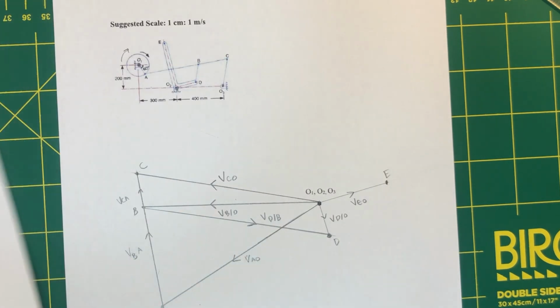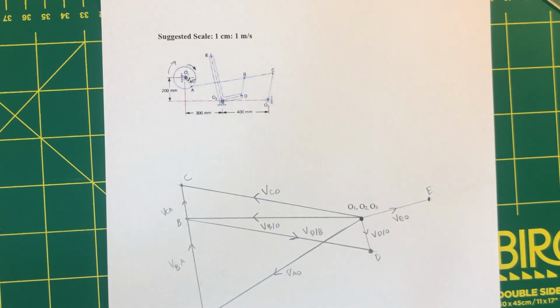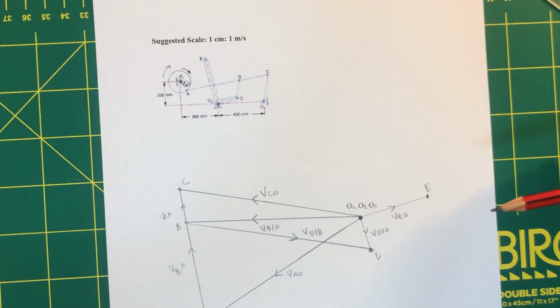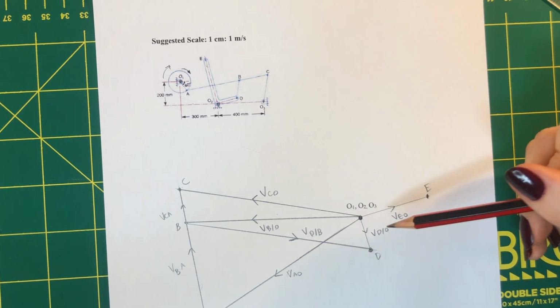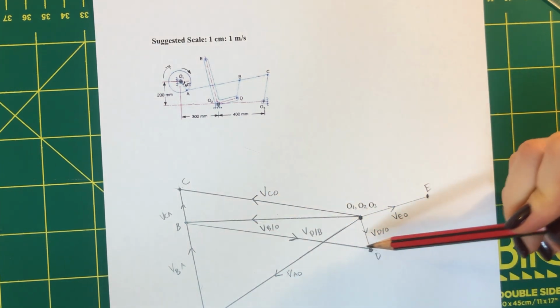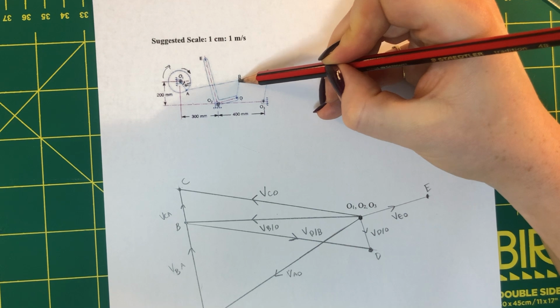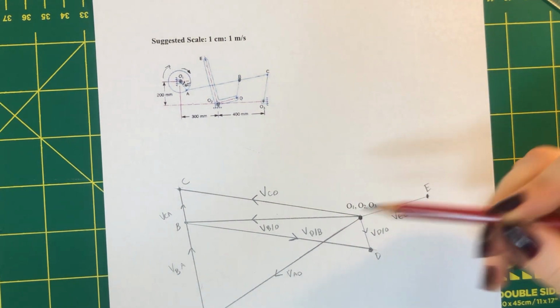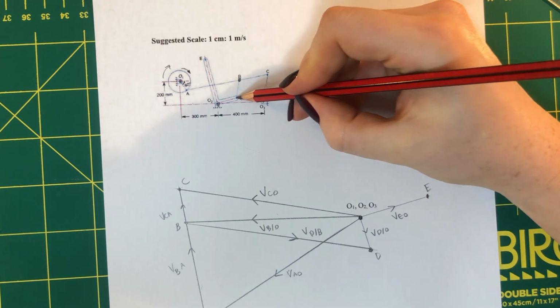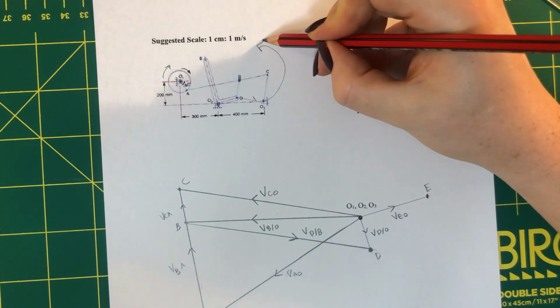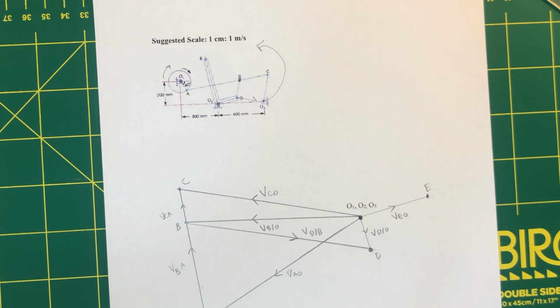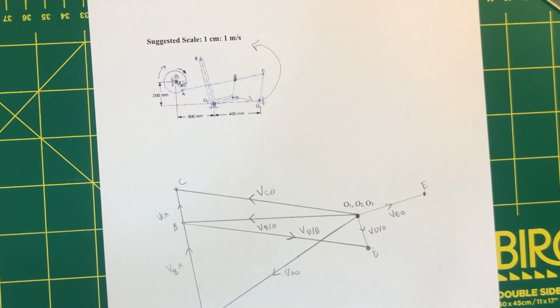The velocity. Again, if you were asked to find angular velocity of any point, the calculation would be velocity on the radial length, and then you need to state the direction. So to do that, if we had D relative to B, that means B is my center of rotation here. So D is moving about point B. I pick up the line DB, move it to point D, and see which direction it's rotating about point B. So that would be in the counterclockwise direction. So my angular velocity of DB would have to have a counterclockwise direction in your solution.